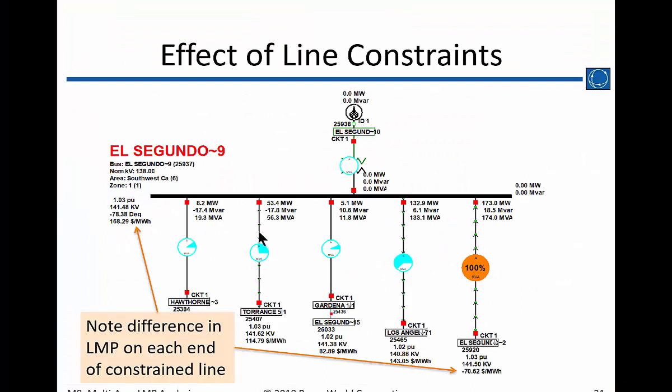And there's also this particular one-line diagram from the El Segundo 9 bus reveals that this generator's offline too. So putting this generator online would probably give some more options. It still might solve at a point where the line is binding. It may or may not, but we would expect that putting that on would cause the price to possibly drop or certainly not go up.